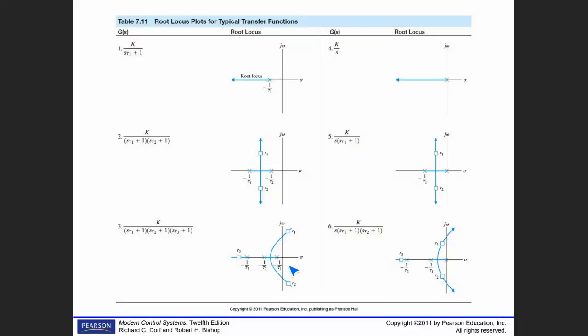Just select it like this. Doesn't matter. It could have been selected for a small value of k. It might be at this point as well. Of course, we are not stupid to select a k value to give us unstable operation. So we are going to select those red ones, for example. Even that one is oscillatory. I would select all like this. 60 degree, 45 degree, between those is giving us the best.